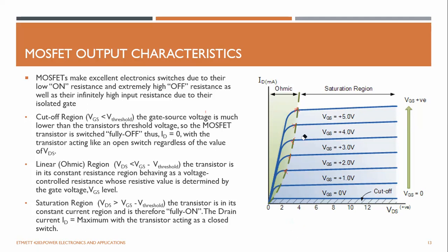And the saturation region is where you have a constant drain current while you can increase the VDS, but that is not of interest. In most power electronics applications, you can either operate your device in the cutoff region or close to this linear region, in the ohmic region. Simply, the resistance RDS(on) times the output current will determine the voltage drop across the drain to source.